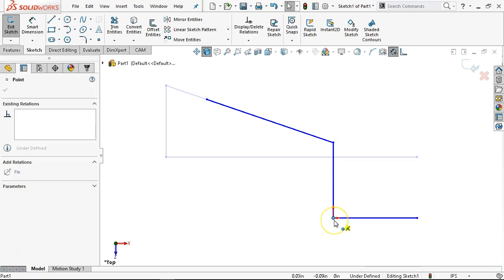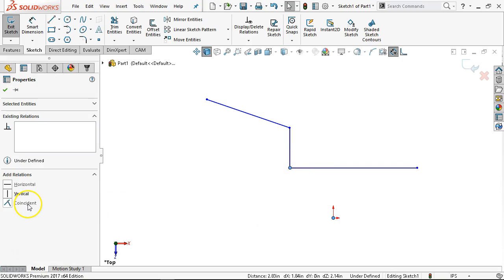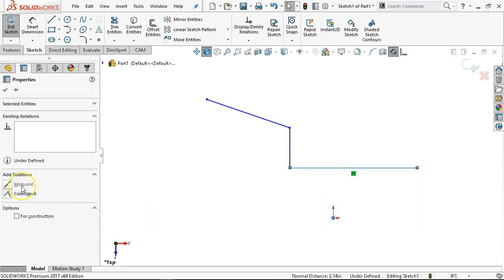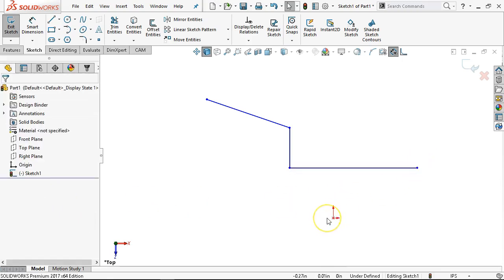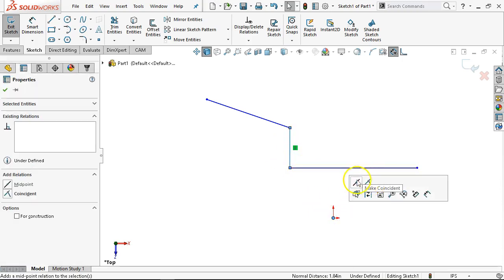Then I can drag something back to the origin, and it doesn't necessarily need to be an endpoint. But as soon as I see my little yellow box that says this is going to be coincident, or I choose to do the select control select, in which case I would have coincidence, or if I pick on the line, I would have the midpoint, or the other endpoint. Basically those are my choices, and it doesn't have to be the horizontal. Go ahead and pick the midpoint of the vertical.